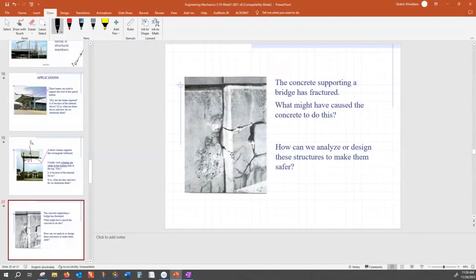So during the bending, the internal forces are a combination of tensile and compressive. What this observation is telling me is that this is a part of a beam, and the portions which were subjected to tension have grown cracks. The portions which are under compression resisted the force.